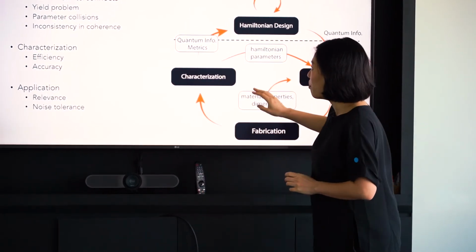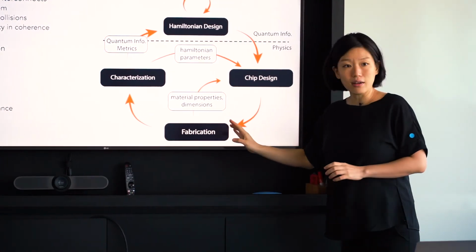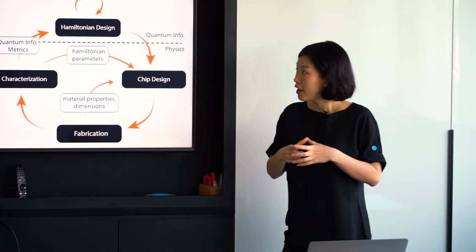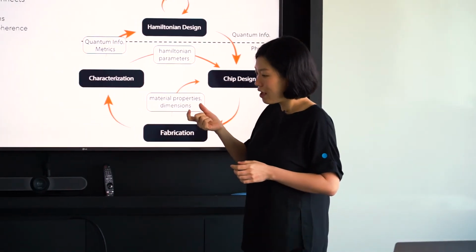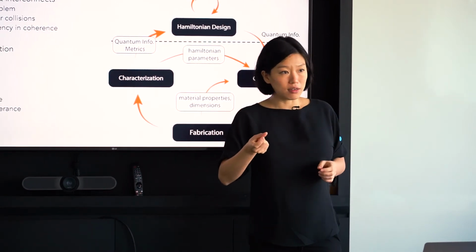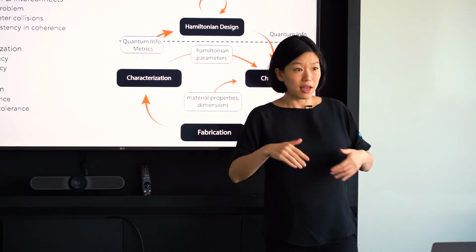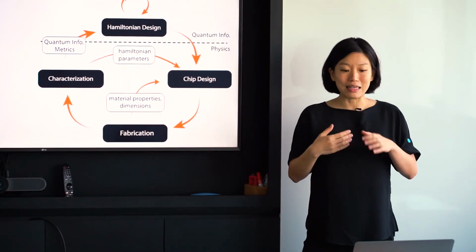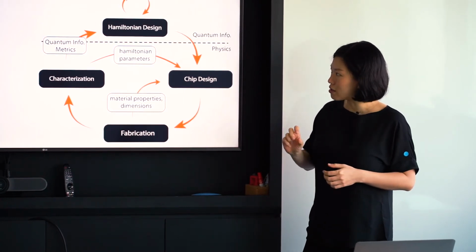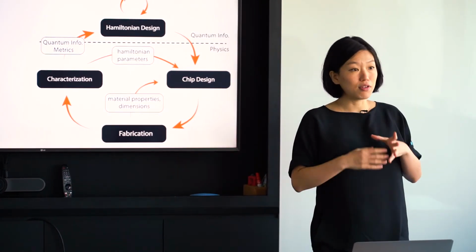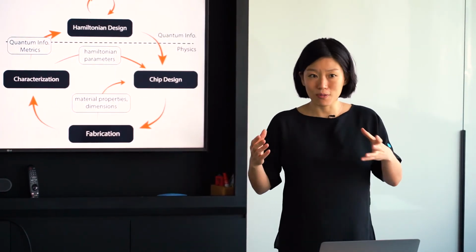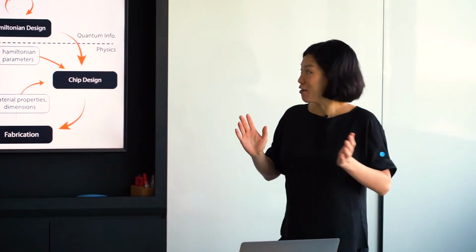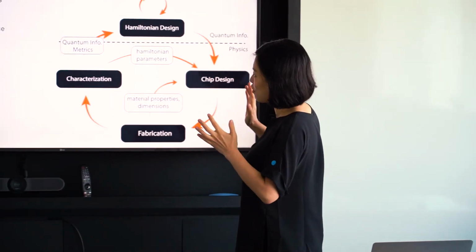So first of all, the fabrication step can be challenging because even though we can make single or small devices reliably now, any imperfections that exist on a single or 2 qubit level, once you push towards 1,000, will be amplified, right? So yield itself could be a problem. When we're making tens of qubits, very often in the Google case, or some of the IBM devices, for example, even though physically they have, say, n qubits on the chip, the ones that they can use could be n minus 5, or I don't know, a different number.